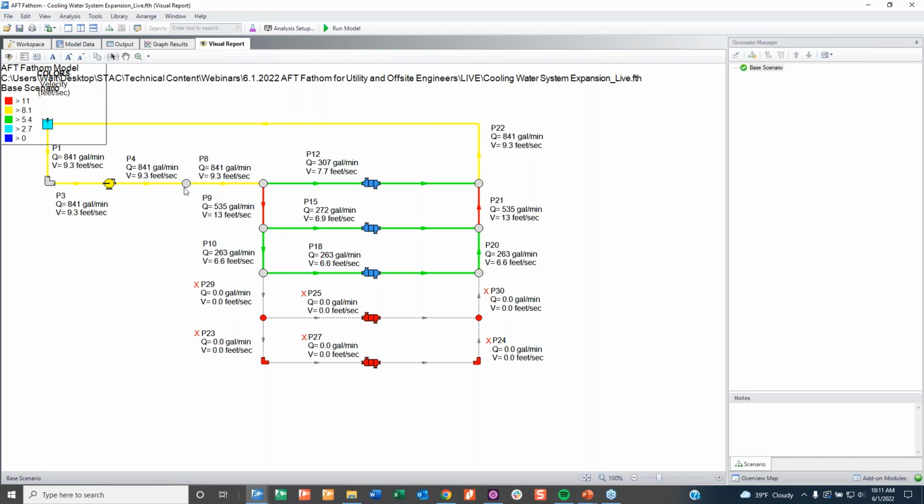But we can see here that as is, it turns out my pump is pumping out 840 gallons per minute. And if you remember my previous slide, our real system is actually only doing about 740. So we're a little too high, and that makes sense because if we're assuming new piping, the friction is going to be a little less. That leads to more flow. So what can we do as engineers to calibrate this model to where I get 740 instead of 840?